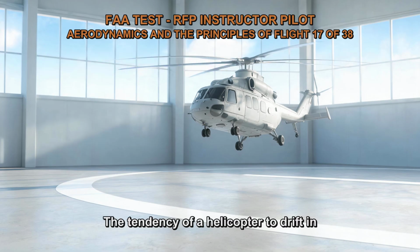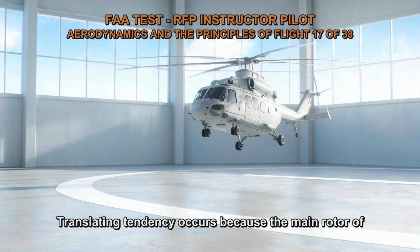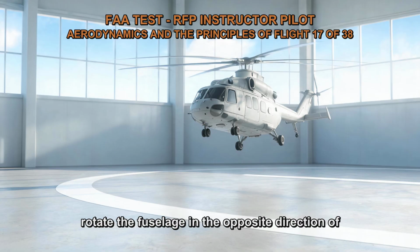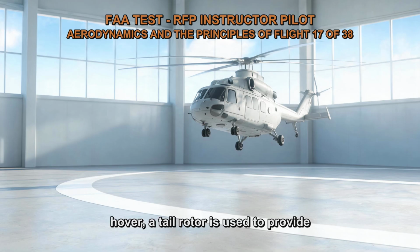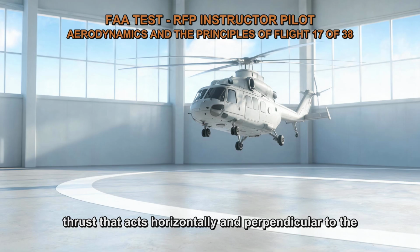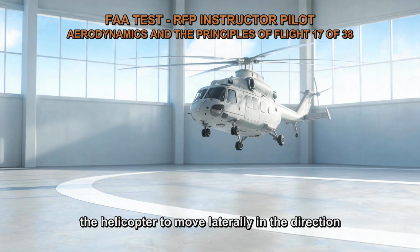The tendency of a helicopter to drift in the direction of tail rotor thrust during a hover is called translating tendency. Translating tendency occurs because the main rotor of a helicopter generates a torque that tends to rotate the fuselage in the opposite direction of the rotor blade's rotation. To counteract this torque and maintain a balanced hover, a tail rotor is used to provide an opposing thrust force. During a hover, the tail rotor generates a thrust that acts horizontally and perpendicular to the longitudinal axis of the helicopter.